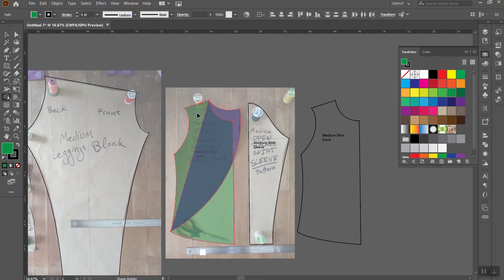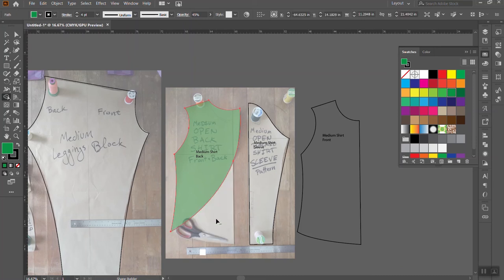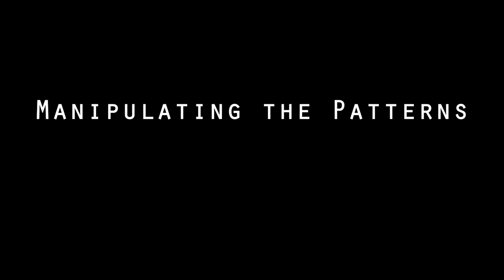And if we click and drag through these areas that we want to combine, they will become one area. So I definitely want the whole top of this to become one area. And if we hold Alt and click or click and drag through areas we don't want anymore, we will subtract those areas. So the shape builder tool is extremely handy.